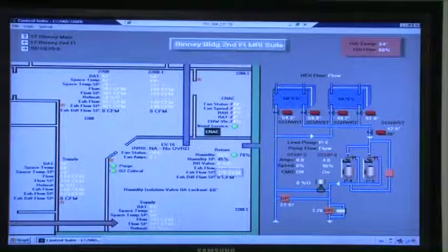So isn't this return right here? It says return. That's your return VAV box. Right. So my return VAV box, I'm assuming I don't have damper positioning on my VAV box. Okay. My return flow should go to 0 then? Yes.